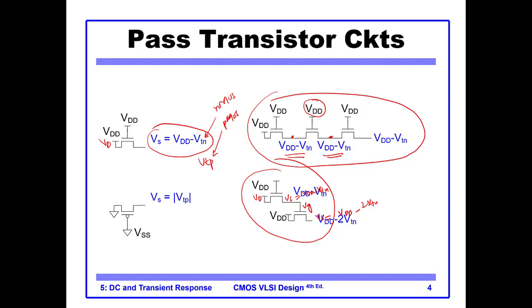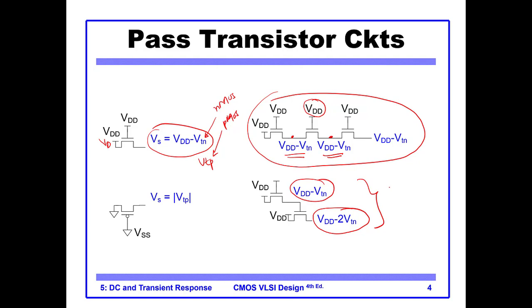So in this case it is sequentially, incrementally decreasing. Okay, you see it's here and it's here. So you should never connect the pass transistors in this cascade manner. So cascading is not a better option, because the signal strength decreases with each cascading stage.